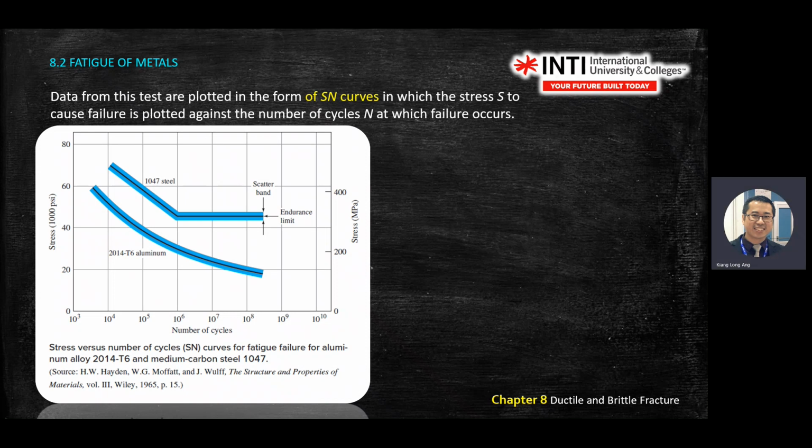So you pick one, and in your report you assume that the material you use is so and so. Then you have the failure number of cycles. So you just simulate the failure point on the graph. Then you project up. There is a range of failure values. Here you got 2 points in megapascal. Okay. Then you discuss this.